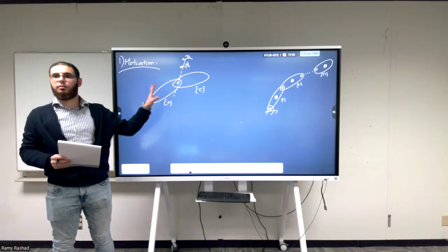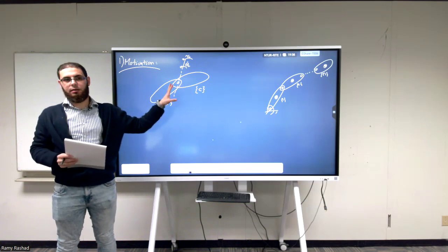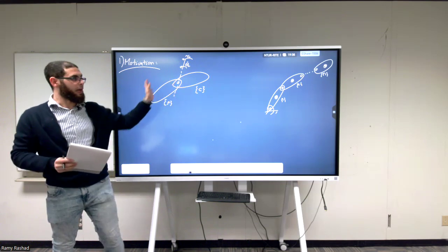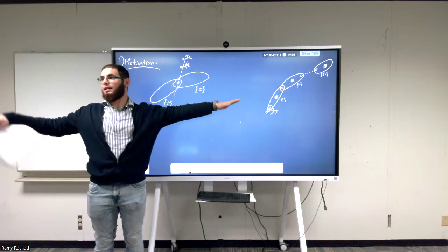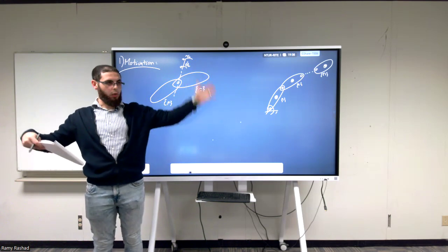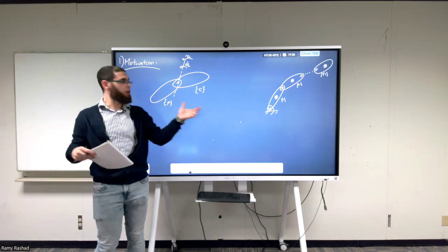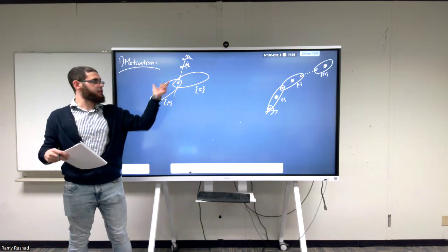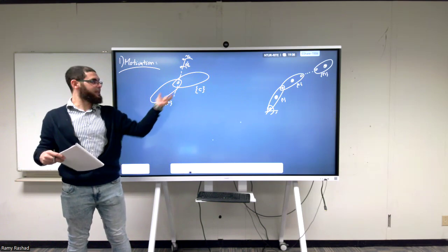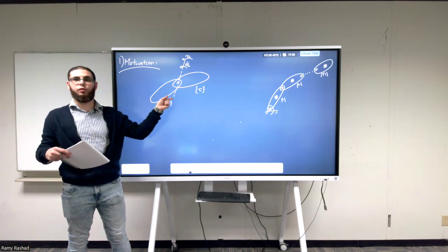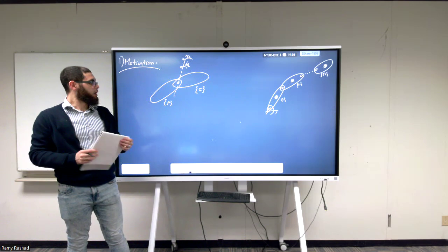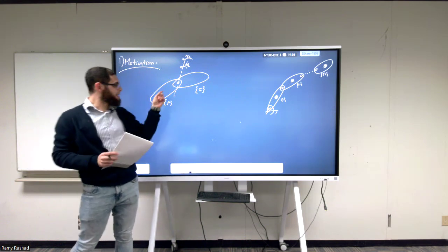If we understand exactly what is happening here in terms of the dynamics, we can simply replicate this from link 0 to link 1 to link 2 to link 3 up to link n. And this is the procedure we're going to be doing. So today's lecture, hopefully we can finish discussing what the dynamics of these two rigid bodies connected to each other with one joint looks like. First of all, how many degrees of freedom does this system have?